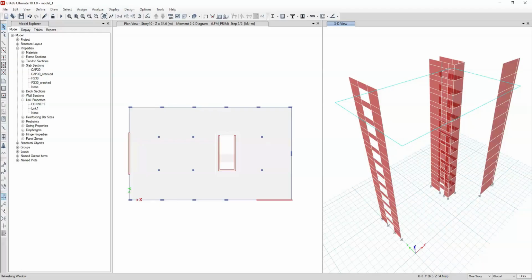What we need is an action that, while perhaps not perfect in terms of seismic definition, has the same magnitude and vertical distribution when applied to the primary structure versus the primary plus secondary structure to allow for a fair comparison. Details regarding the behavior coefficient are not important here either, because the key is having the same action applied to two different structures so that the contributions of the primary and secondary structures are comparable as a percentage. Therefore, to be clear, what we want to ensure is that the stiffness of the secondary structure contributes less than 15% to the stiffness of the global structure. To achieve this, we are going to compare the story drifts or displacements for both scenarios. We will now define our equivalent static action.